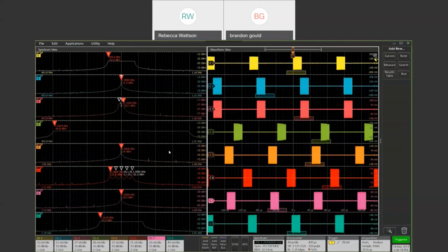So you can see where it's just one single continuous signal. A 1.1 gig chirp right here, a 1.15 gig LFM, which is 250 megahertz wide. And then we have an up-down chirp, a 5-step, another continuous wave, and then an 80 megahertz wide LFM.